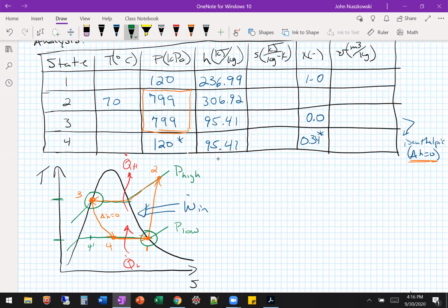And in a real life application, would that expansion valve require any work input, or is it just? No, it's just restricting. It's just a small orifice. Just think of it as a valve. In reality, an expansion valve usually controls the size of that orifice because it regulates the flow. It might have a temperature gauge connected to the valve to open and close itself to allow more or less. But it's basically just a restriction.